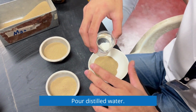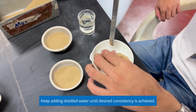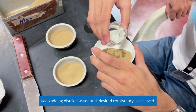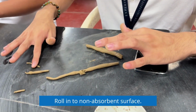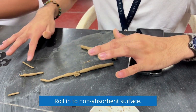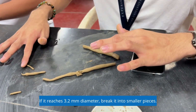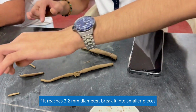We pour the distilled water into the soil. We keep adding distilled water until the consistency of the soil can be rolled without sticking to the hands. We form the soil into an ellipsoidal mass. We roll the soil in our hands on a non-absorbent surface. The thread of the soil shall be deformed in order to reach a diameter of 3.2 millimeters.